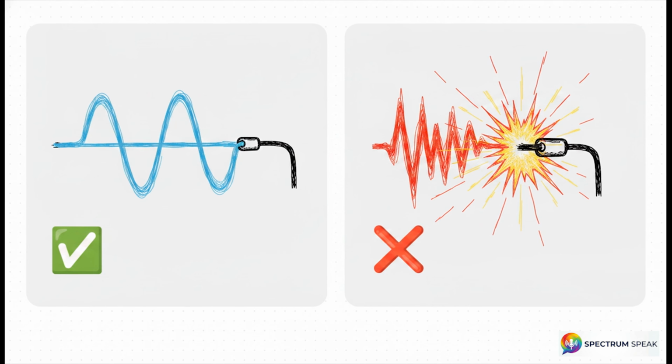But today's digital circuits, they operate well above 100 kHz, often pushing deep into the gigahertz range. And as we just saw mathematically, at those high frequencies, that exact same pigtail completely falls apart. It acts as a massive inductive bottleneck and a powerful capacitive antenna. It's just a fatal design flaw for modern EMC.